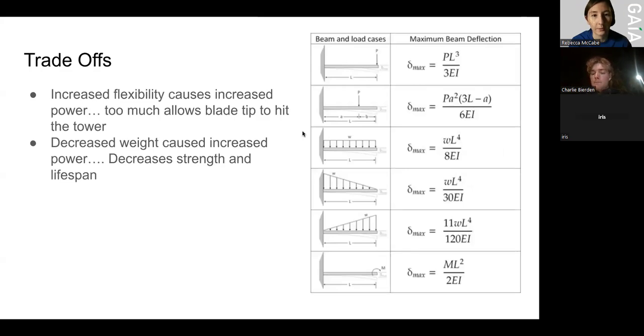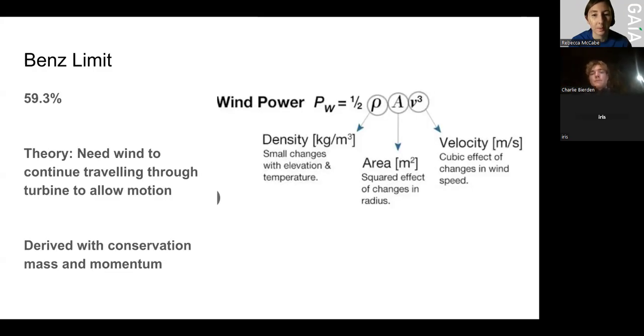One thing I'll add on to that previous slide is that the power equation, the velocity that you put into that is an instantaneous velocity. You can't put the average velocity into that equation and get an average power, because the cube of an average is not the average of a cube, if you think about how it works statistically. So if you're trying to get the average power for a whole set of velocities, you might have a time series for what a standard hourly velocity profile over time is in Peru.